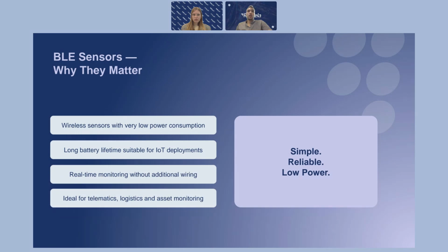If you install a regular temperature sensor, let's say one wire, usually it requires you to do the wiring. It's a hassle during the installation. And sometimes, due to corrosion or the environmental conditions, these types of sensors require regular maintenance. BLE accessories, or a BLE temperature sensor in this regard, really solve this issue. Also, because of the long battery life, mostly your maintenance would be just to go and change the battery.